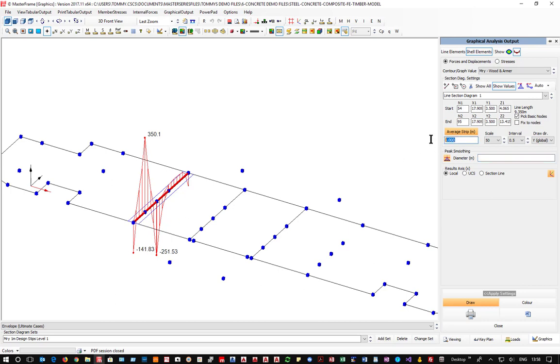So if we are able to not design the 1 meter width but the full 2 meter column width, then we actually drop down again from 470, 350 to 76. So we're taking a wider width of design, and we're able to get a more average reinforcement. Obviously, under such quite high point loads, you may want to consider other things.